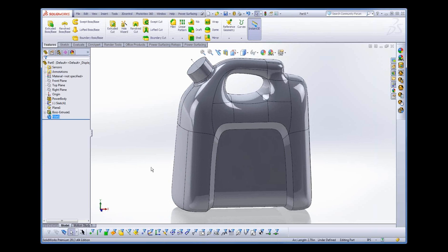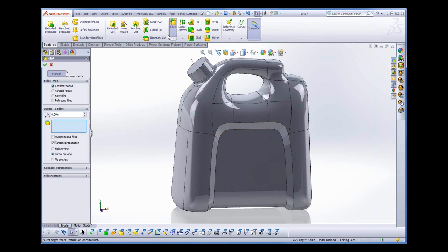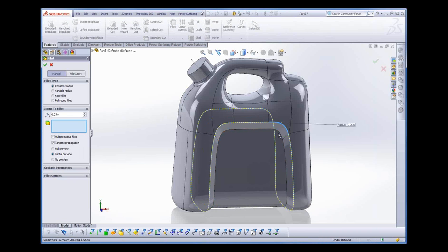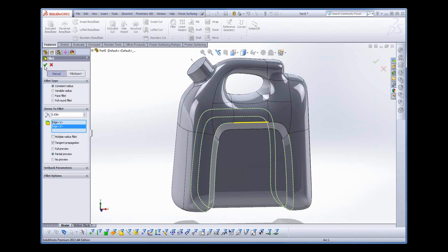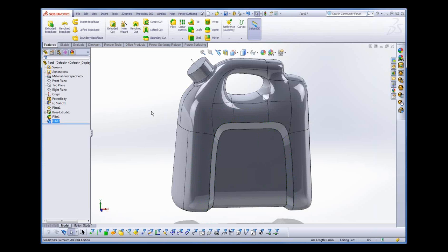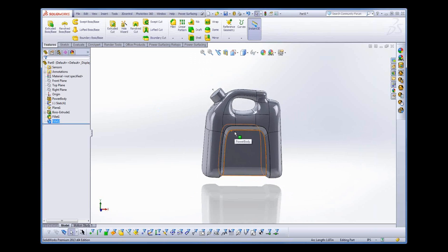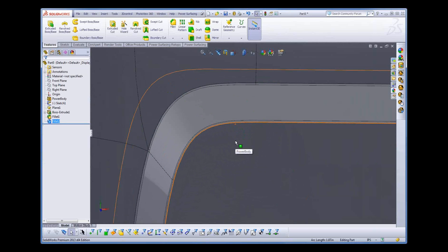Now it would be really nice to add some fillets over to our creased edges, our edges that had 100% weight. And that's one of the things that we're able to do with that hard edge. So I'm going to open my fillet again, set this one to 0.05, and select some edges here, and say OK. So there we go. Got some nice little bitty edges. If I zoom in, you can see them where they've been filleted.